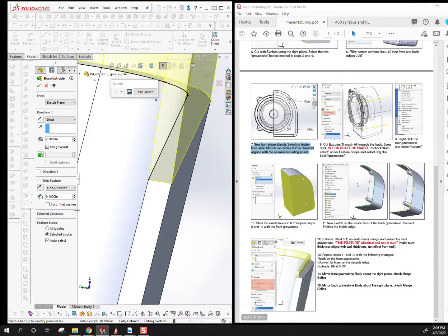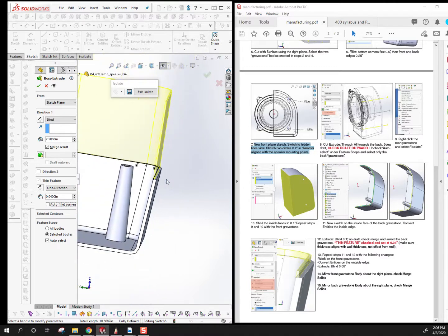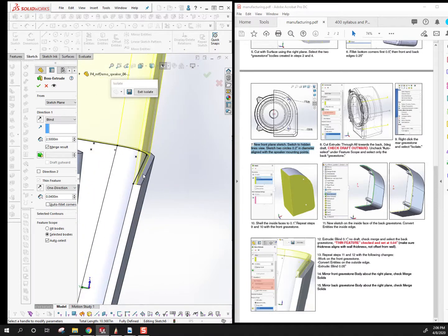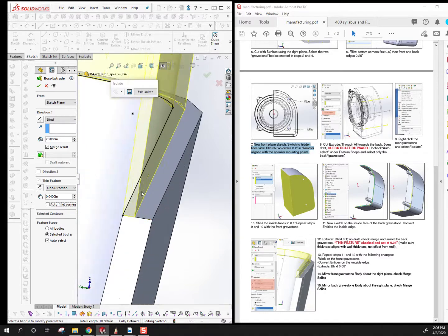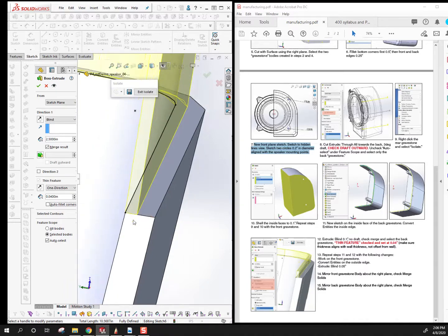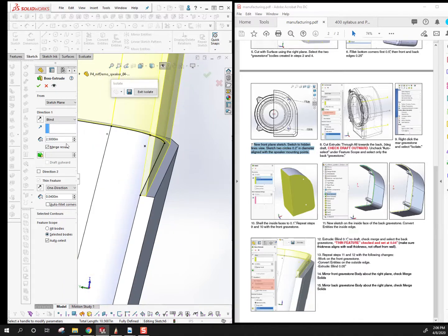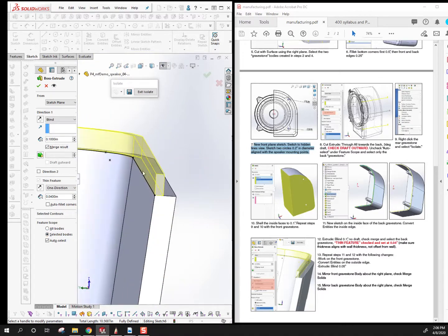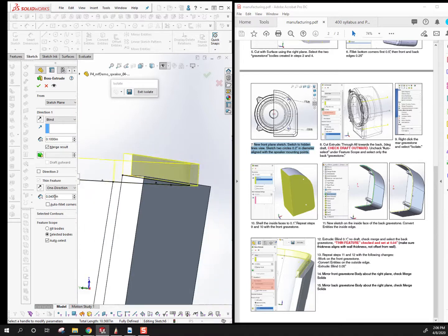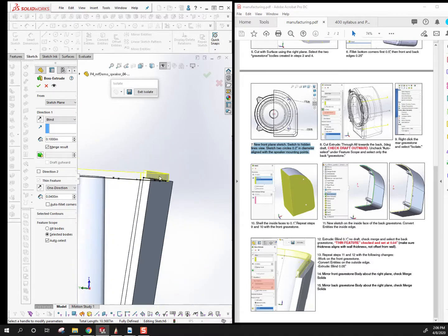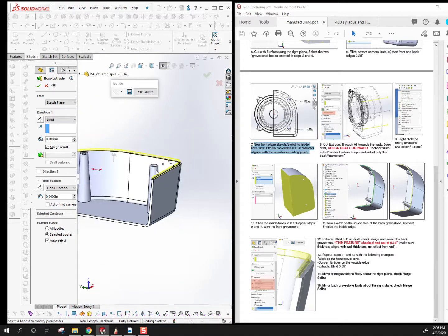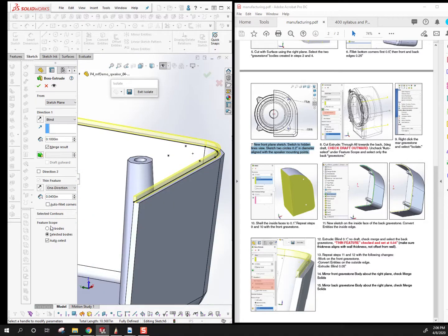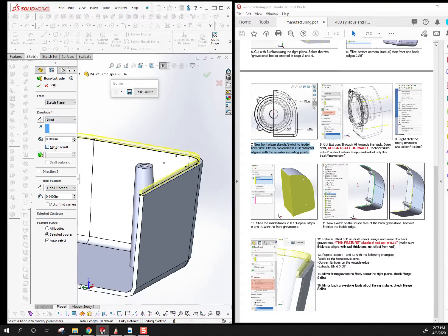What is the thin feature? It's set to 0.04, which is 1 millimeter. So there you go. This is 0.04 wide, 1 millimeter wide. And then as far as the direction goes, we just want this to be 0.1 tall. Now some of these settings are important. This 0.1 tall is closing the gap in the part line. And again, this is where that merge result becomes important.